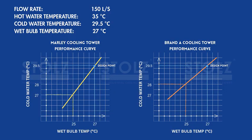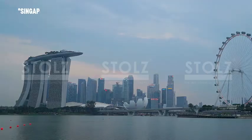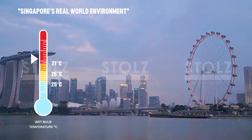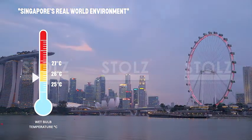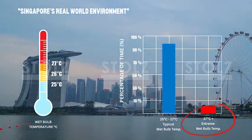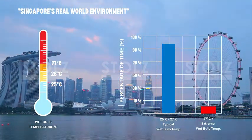When comparing the performance of two different brands of cooling towers, what should we be looking at? Which is a better tower? Both towers meet the design point of 29.5 degrees Celsius and 27 degrees Celsius, cold water and wet bulb, but which is a better tower? In Singapore's real-world environment, the wet bulb temperature is usually between 25 and 27 degrees Celsius for more than 50% of the time. This means that most of the time, conditions are moderate and within a common operating range. The more extreme wet bulb temperature of 27 degrees Celsius happens only about 5% of the time, and even then, we may experience it only for a short period, typically just a few hours.